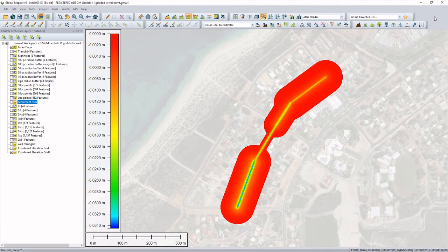If the front half of the building settles more than the back half, it doesn't matter necessarily how much the entire building settles as a whole unit, total settlement, but that stretching which occurs when a slope occurs because the front settles more than the back can be particularly damaging. So I'm going to want to look at both total and differential settlement by looking at my settlement as contours in millimeters and settlement as slope. And Global Mapper gives us those tools.